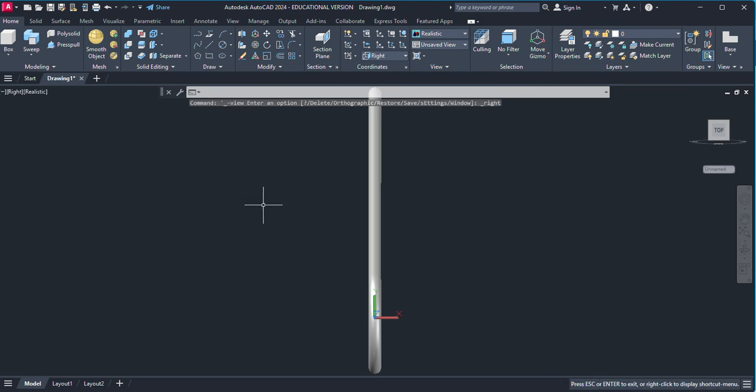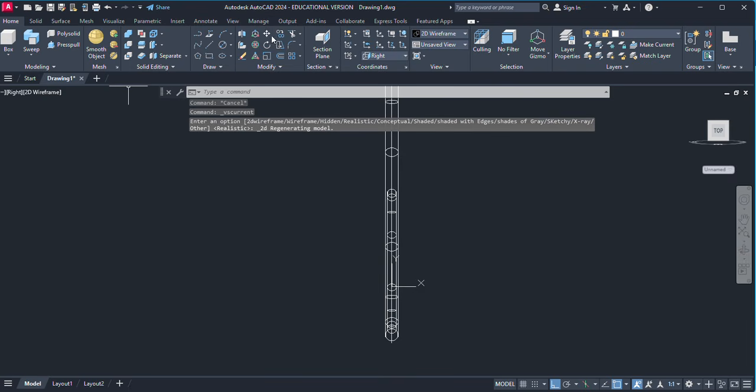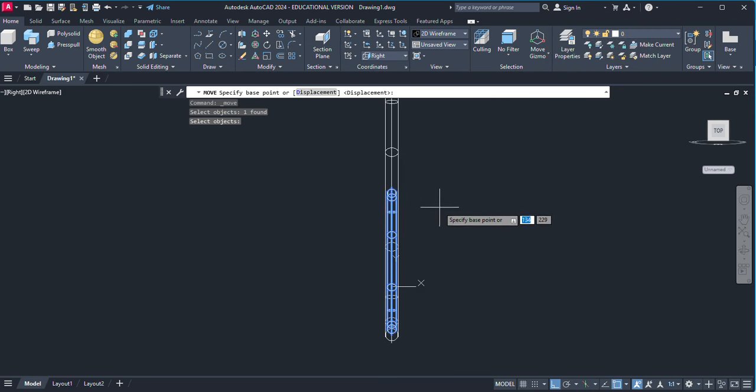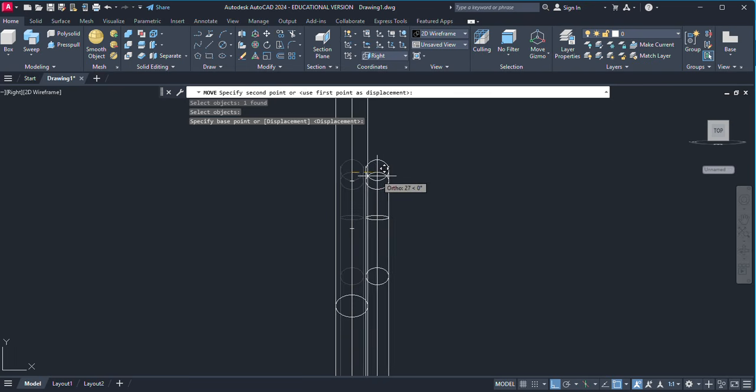And you go for this side, right side view for your reference. It is not merged together like that. That smaller part is a little bit inner, on this side or this side. So we'll move on to this diameter, we know. This is 35 mm. So 17.5 mm, on this side it should be moved. Keep it in wireframe and move. Select the smaller object. Carefully select. Okay, enter and move it accordingly. Move this side.